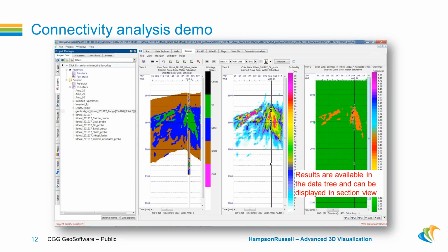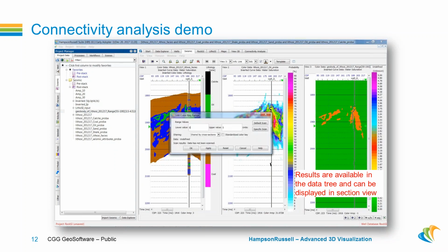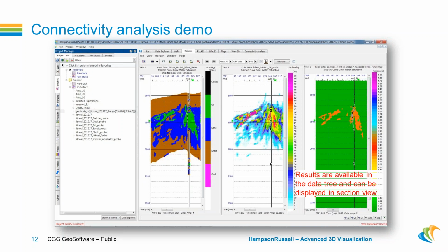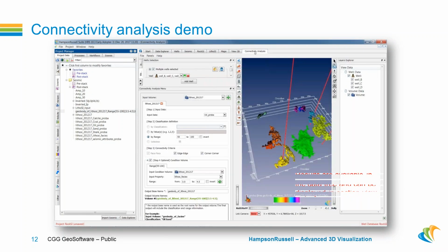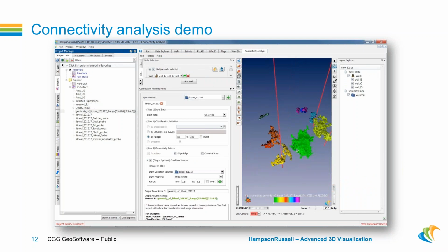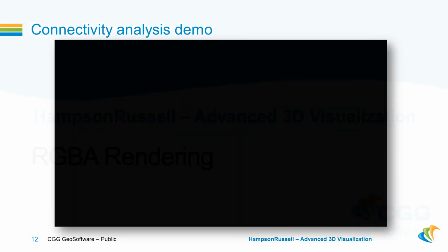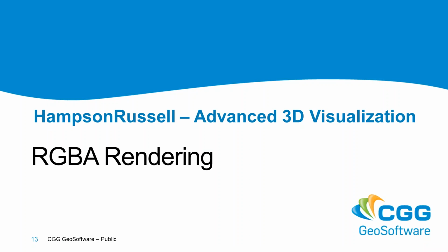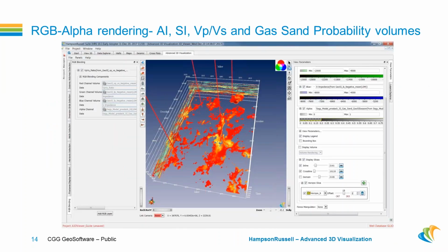Traces, yeah. So this will be the bodies that have been captured. You can change the color scale if you like to display them better. But for the moment, it's looking like orange and green background. And this is the final view of the displayed captured bodies. Next step is blending red, green, blue, and alpha, the different volumes, and applying maybe alpha. Using alpha, you can just apply transparency.